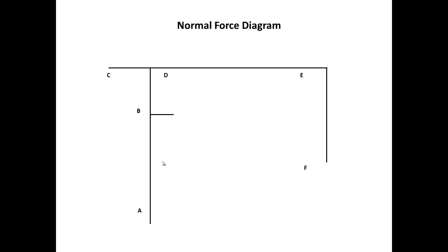For the normal force diagram, you take the diagrams you drew for each member and just assemble them into the general frame. So this one is the 11 kilonewtons compression, and try to keep whatever value is negative inside the frame, in the inner part of the frame, and whatever is positive, keep it outside, so you have a sign convention of your own.